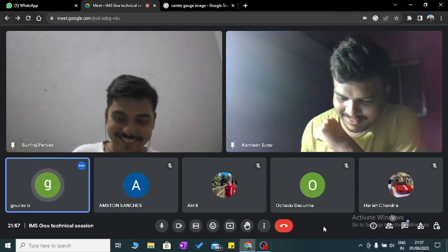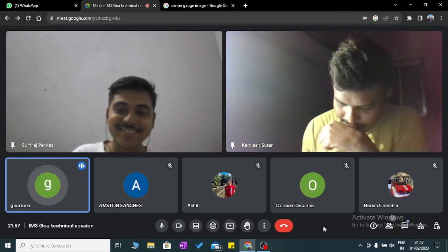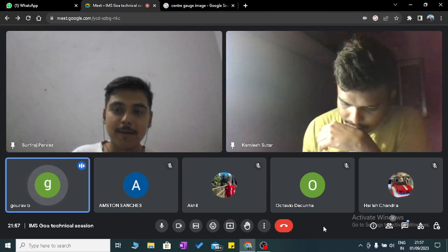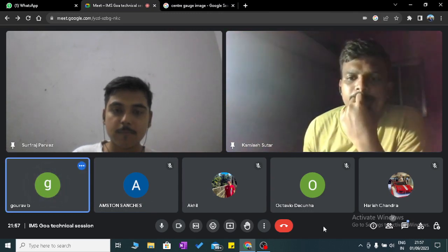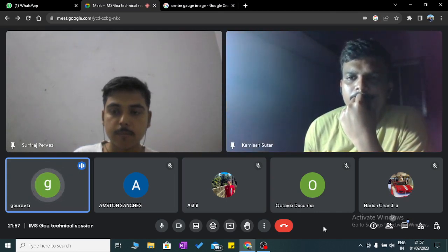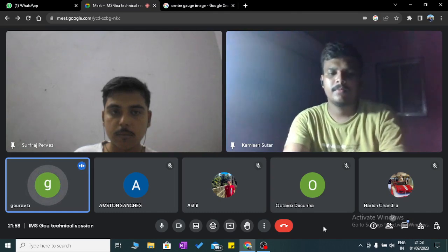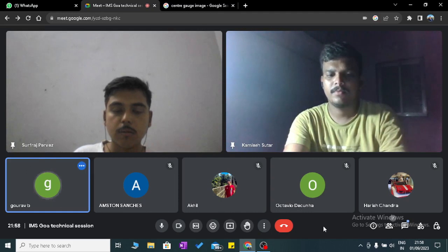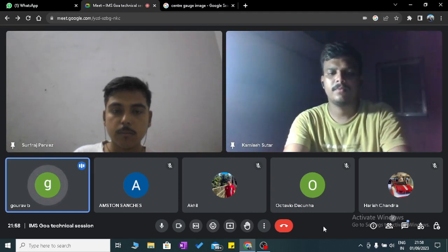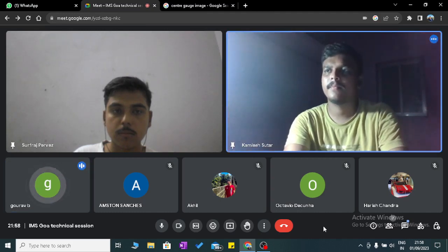No. At first, we do the chamfering because when we give the tool, the cutter, to the job, a high stress will be created on the single point cutting tool. That is why it can break. That's why we need a chamfer for fixing. Every nut you will see at the starting side of the thread, a chamfer will be done. That is the reason for the chamfering.